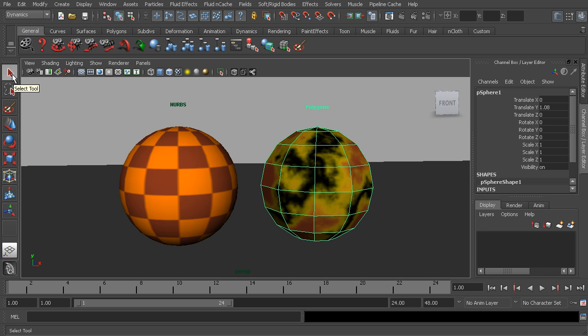So our discussion for the time being is going to really focus along these tools that are on the left-hand side of your interface. These tools have keyboard shortcuts, so this is where we're going to get into our selection tools, our move tool, rotate, and our scale tool. The keyboard shortcuts for these correspond to the top row of alpha keys on your keyboard. So this is going to be Q, W, E, R, T, and Y.